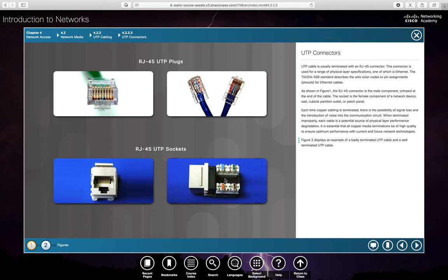You bring the wire in, and then you pull the wires like the orange wire, orange and orange-white, brown, brown-white, green, green-white, blue, blue-white, and then you have something called a punch-down tool that drives the wires in these little slits and makes good connection with these metal pins in the middle that are going to press against the pins in the RJ45 connectors.